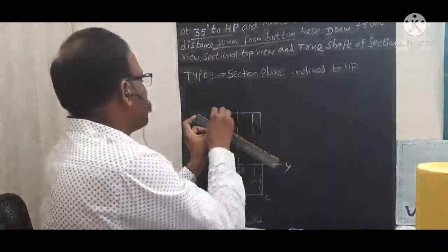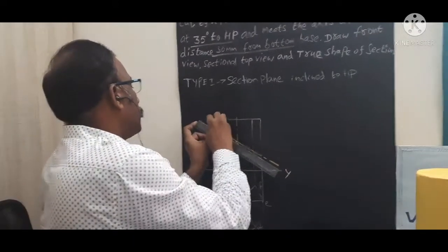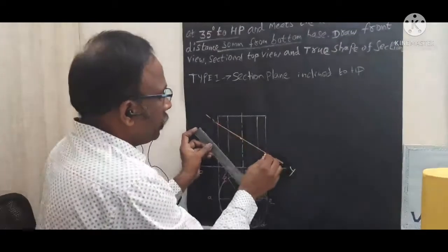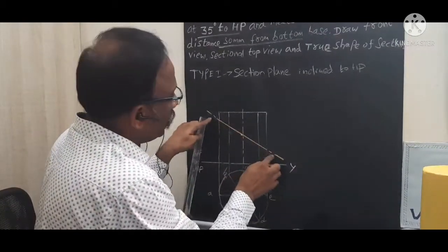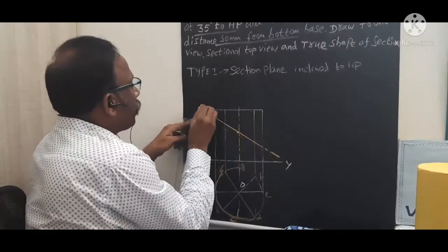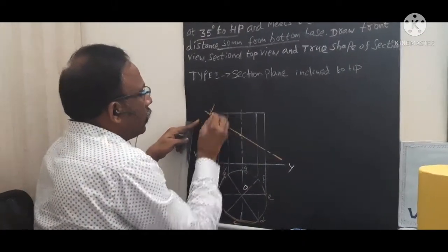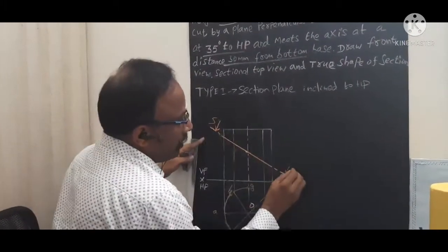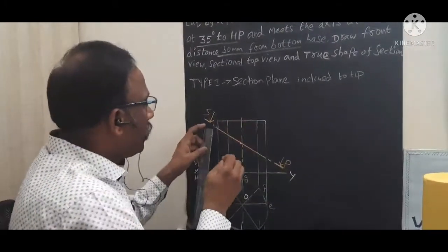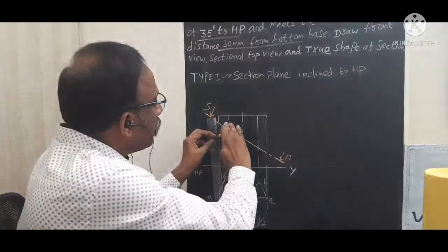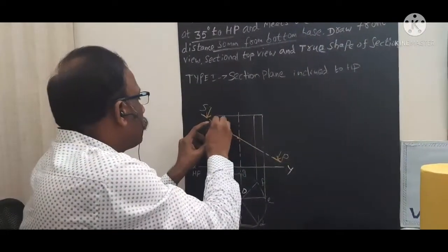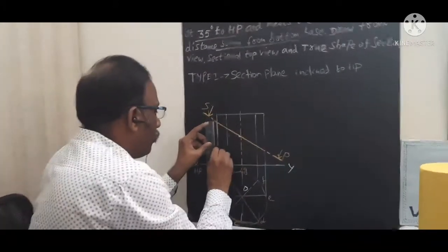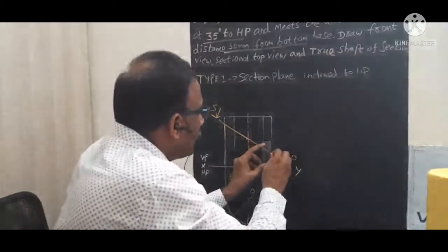So how do we draw the hatching lines? This section plane line, this is the way you can darken it. After this section plane, you need to draw one small dot, then a big line, right? Now you represent it through this arrow. Then we can represent this as S for section, P for section plane. Now only the remaining portion is visible, because we are cutting and removing the top portion. Only the bottom portion of this particular cylinder we need to give this darkness, on these sides.